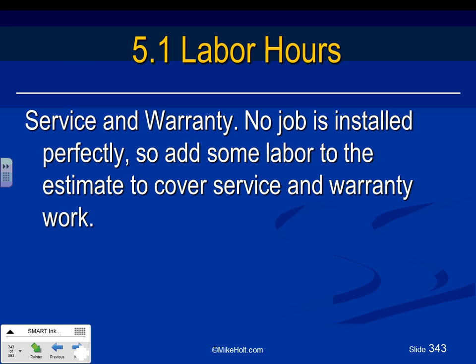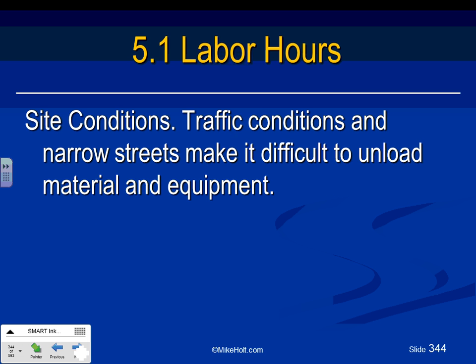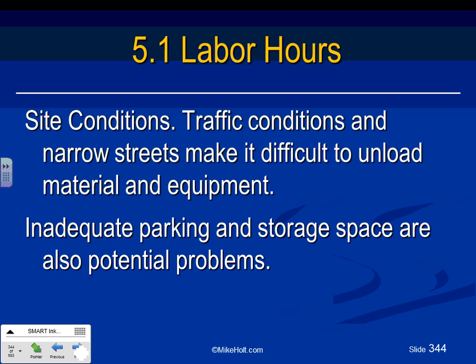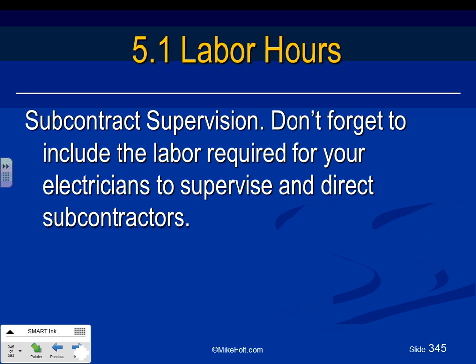Service and warranty. No job is installed perfectly, so add some labor to the estimate to cover the services and warranties you're going to be doing. Site condition. Traffic condition, parking, unloading and loading material in downtown Minneapolis, guys. When you send Ace Electric there, it will take longer to park, longer to find a place, longer to unload and load. So that has to be taken into consideration. Parking and storage spaces are potential problems for projects.